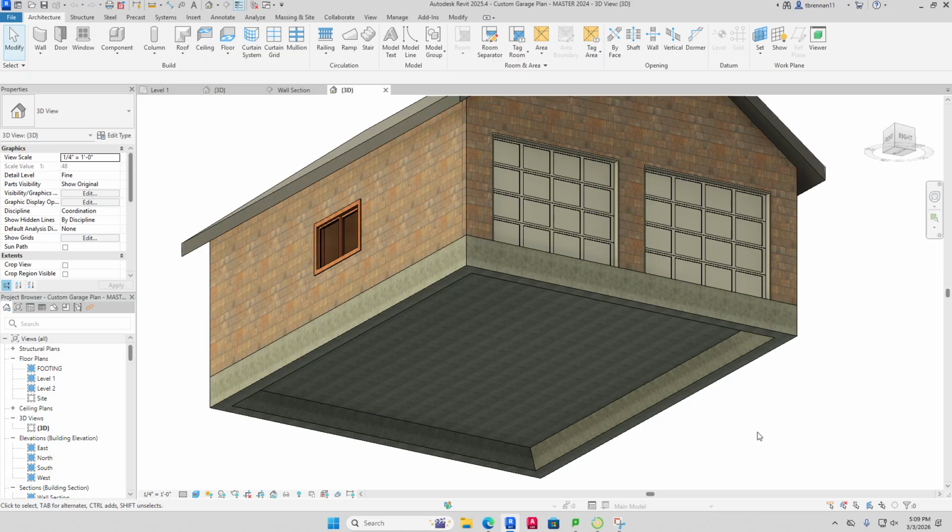Around the perimeter. Yeah, okay. It's foundation. It's actually a slab edge, is what they call it. What they do is they thicken the slab and make it deeper on the edge, so it's kind of like a tooth around the perimeter, digging in. You put this on when you have a slab like this to keep it from shifting. It's commonly done. And so when you've got something like this, that is how we have it.